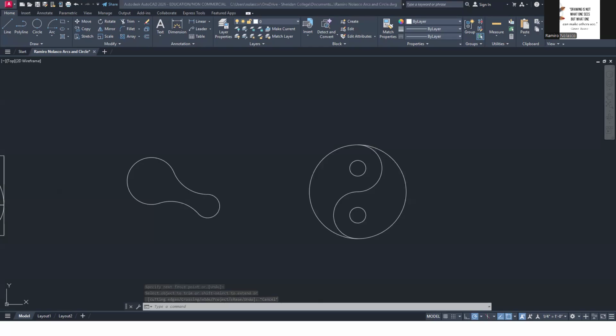Okay, so that's a good practice. Save, Control S. Sorry, how do we select the colors? So hatch, HA, enter, select solid, and then right here, you can select the color.